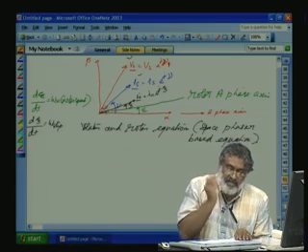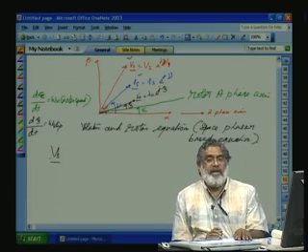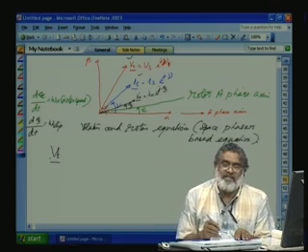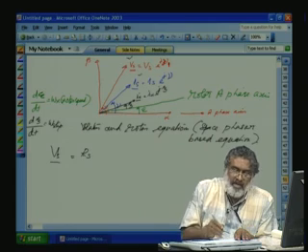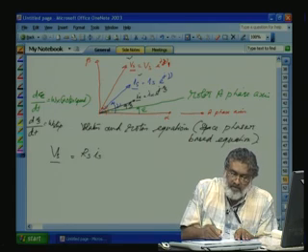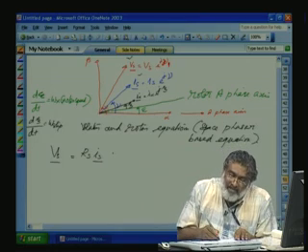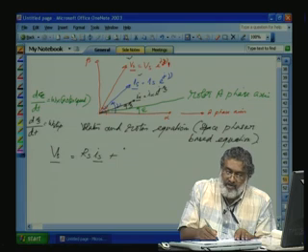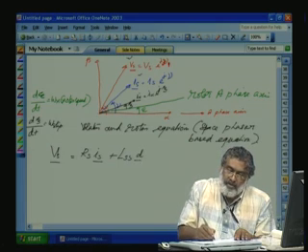Let us start with the applied stator voltage Vs. When the stator is applied with a space vector Vs, it will have the stator drop. This is the space vector Is plus the stator self inductance, mutual plus leakage, that we will represent as LSS. This is called self inductance, into d by dt of Is.